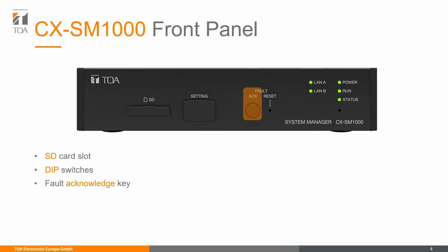If you want to reset the fault manually, you can do this with the fault reset key. This is hidden behind a small hole. On the right, we have some status LEDs, and finally, again behind a small hole, we have the device reset key. This key will restart the system manager.